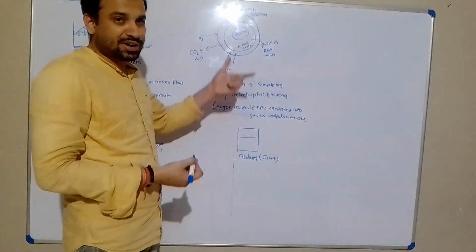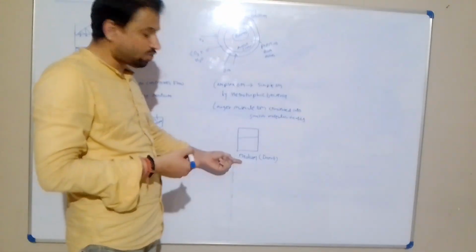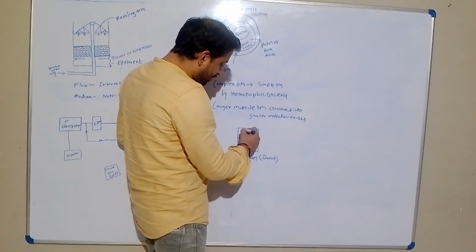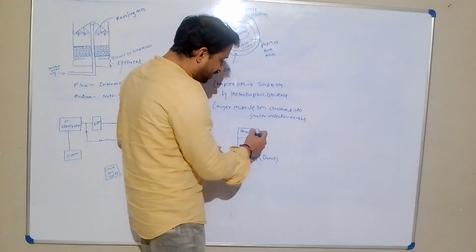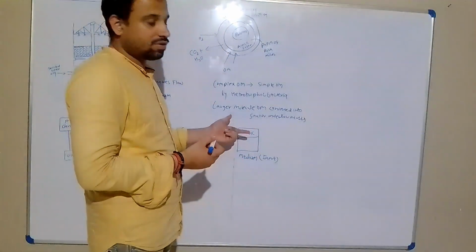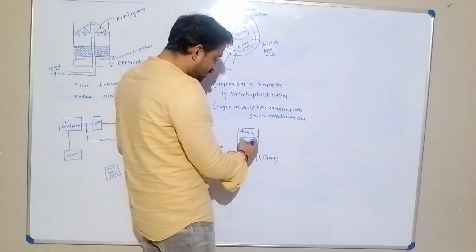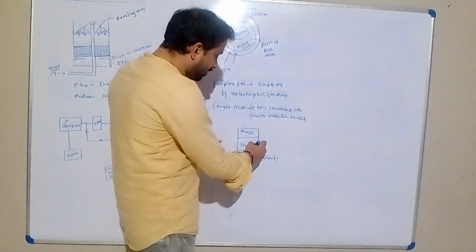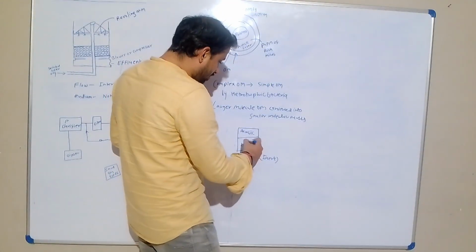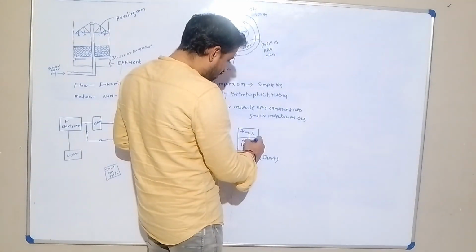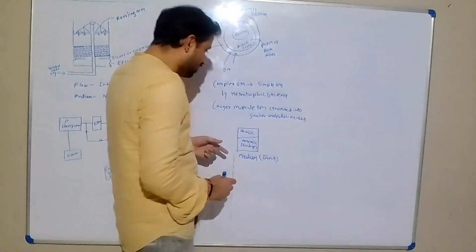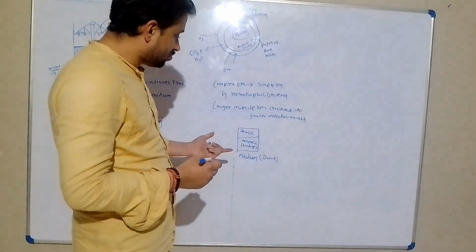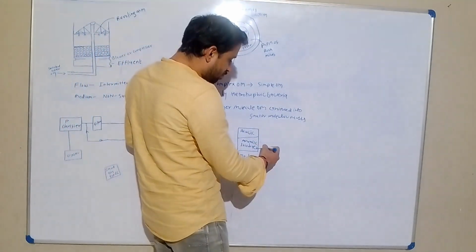The inert medium is provided for the wastewater to trickle over. Generally, aerobic condition takes place in the upper layer or outer layer of the biomass, and anaerobic condition takes place in the lower layer. So depletion of O2 is more in this layer.